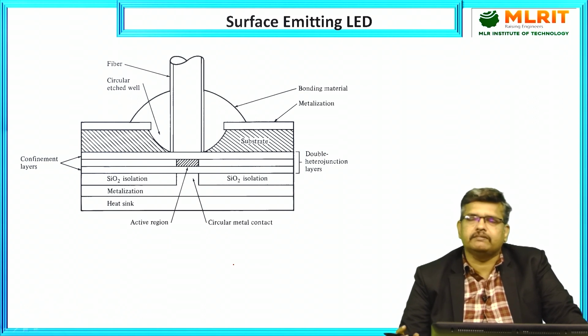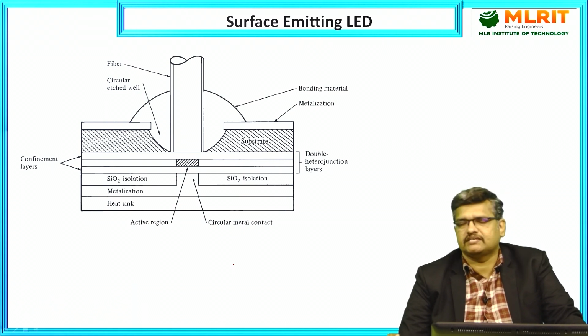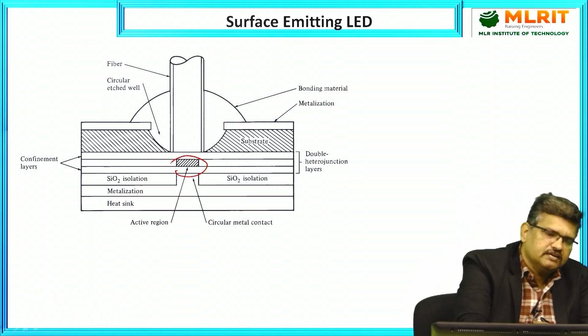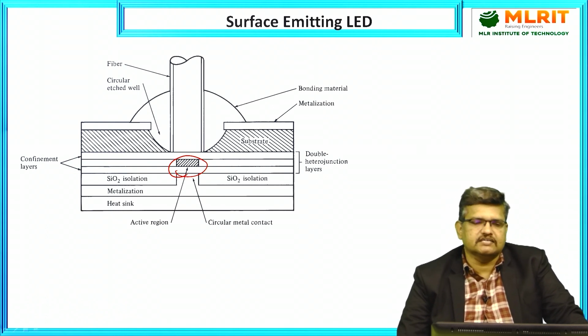The LED is a light emitting diode. The main thing is electron-hole recombination, which produces photon energy in the form of light. That's why we call it a specialized diode: in a normal diode, electron-hole recombination also occurs, but here it emits radiation in the form of light. You can call the emitted energy photon energy. In the active region, the radiation is present; that is the light source. So let us come to the configurations.